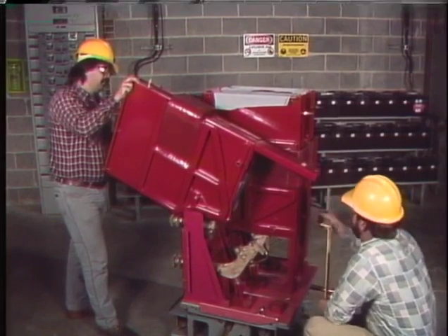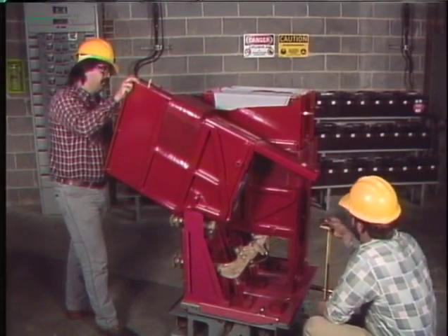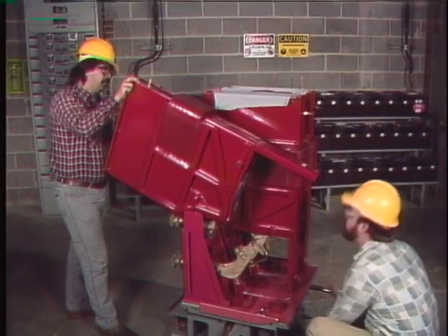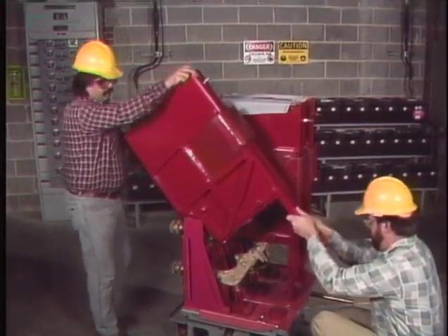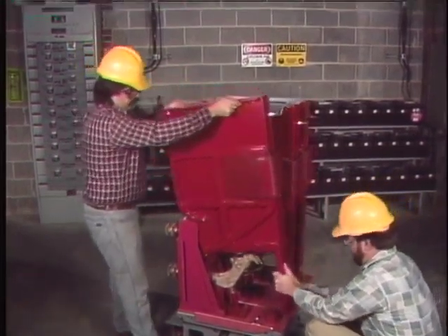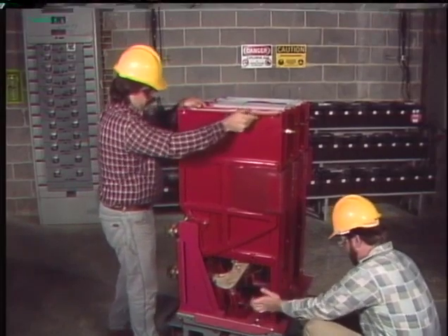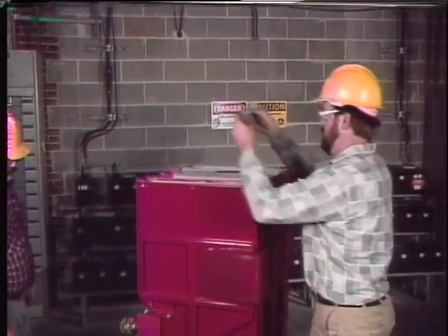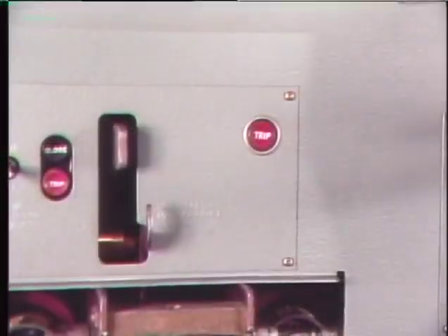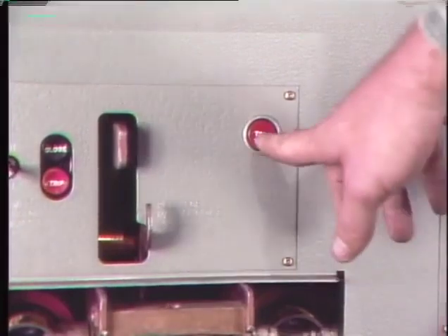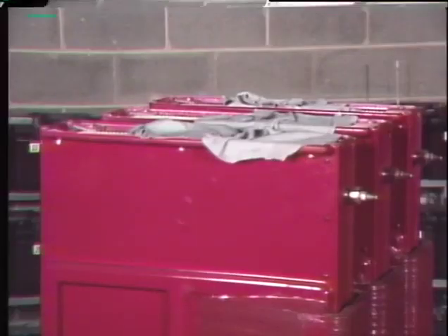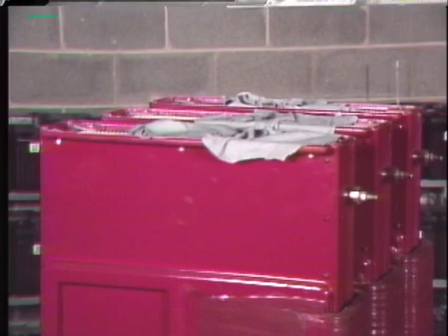Finally, the operation of the puffers can be checked. First, the breaker is opened for safety reasons. Then the arc chutes are carefully put back in place. The breaker is manually closed, and clean rags are placed on top of the chutes. Care is taken to stay clear of the mechanisms, and the breaker is tripped. If the puffers are working, a short blast of air should lift the rags off the arc chutes.